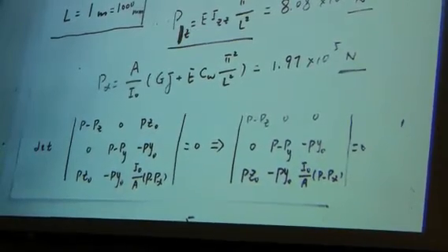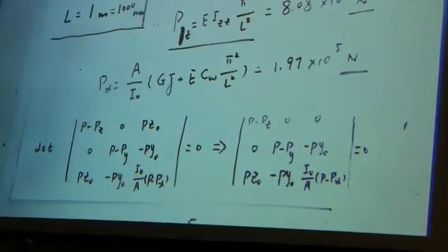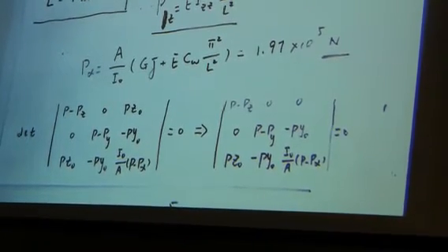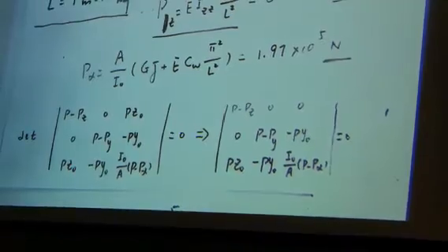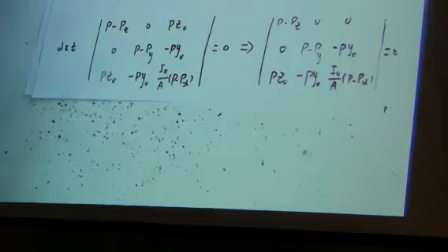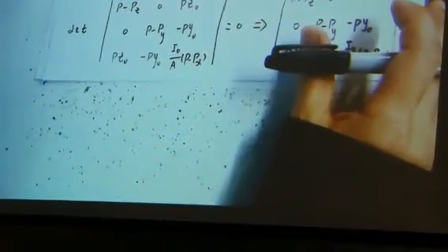You have four values for P actually. After the calculation, you will have four values: Py, Pz, P alpha, and the P you calculated from that equation. So you should choose the minimum value of these four different numbers. Okay. So this is the next step. Follow this example, you can do that one in your homework, because I just changed the geometry of the cross section. All of the procedures will be the same. You just calculate the determinants of that matrix.